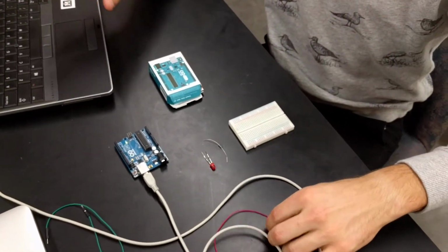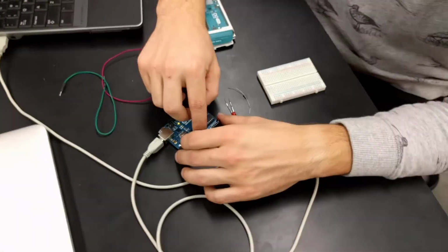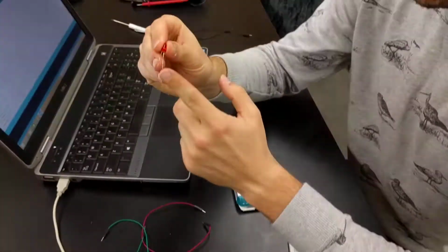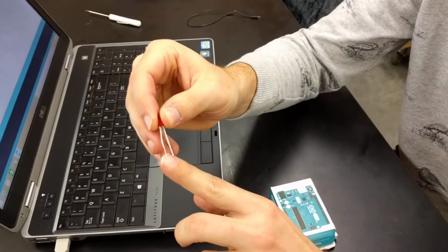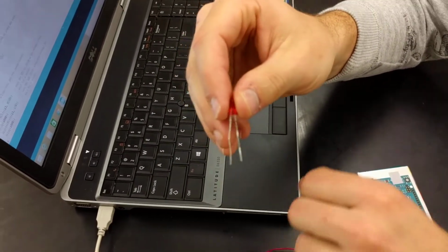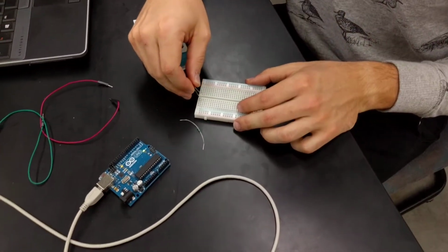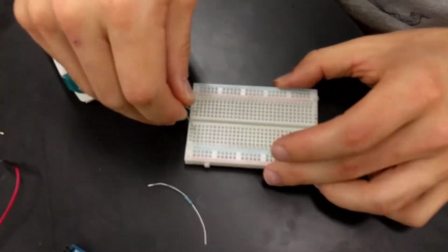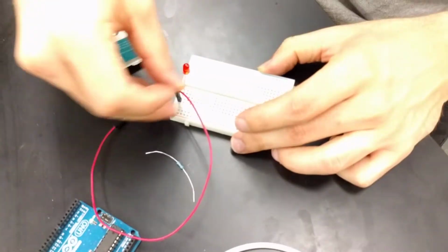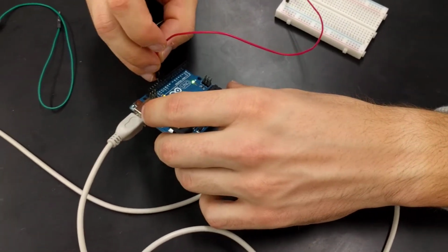Next, we'll be using the Arduino, which has a digital side and an analog side, to power an LED. An LED has a short and long leg. This long leg is the positive side in which you supply the power. LED is an acronym for light emitting diode. Diodes are polar, remember that. I will be using this breadboard to connect the circuit and create a circuit that is powered by the Arduino that then controls the entire system.